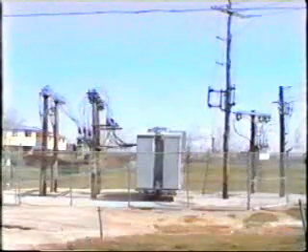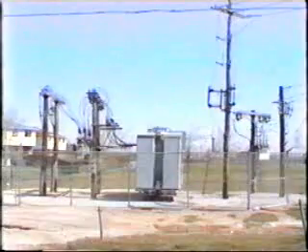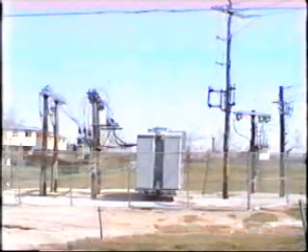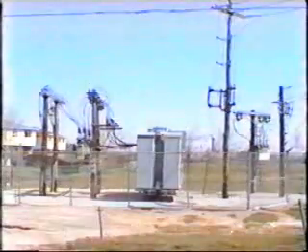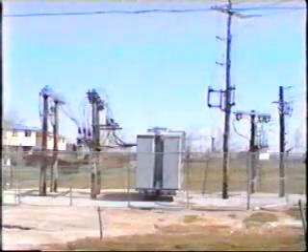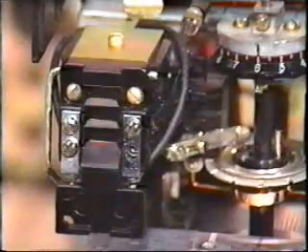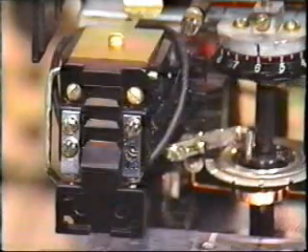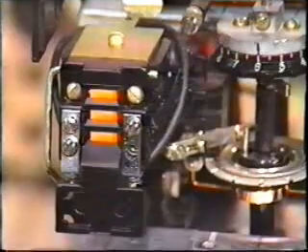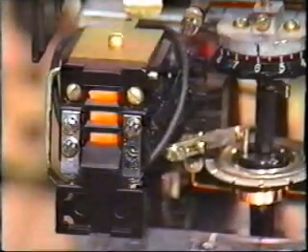Normally, oscillographs are not located at the distribution substations, except those installed to analyze special problems or to conduct research. But it is just as important to analyze incidents occurring on the distribution system as on the high voltage power system, even though you may not have the help of sophisticated recording equipment. In this area, you will have to rely upon operating reports, including relay target data.